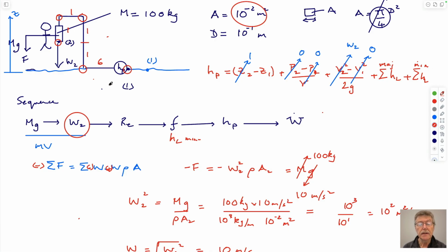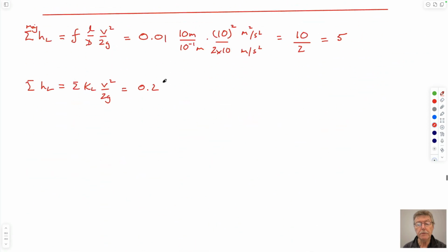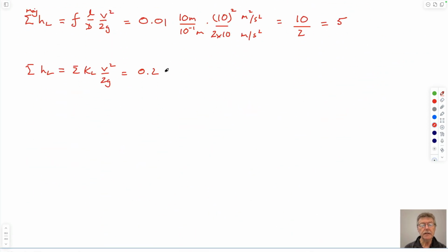This is a bend. And so let's just use K sub L equals 0.2. That was a commonly occurring number we had before. And conveniently, this would be 5 of those, sorry to be so pedantic, times V squared over 2g.